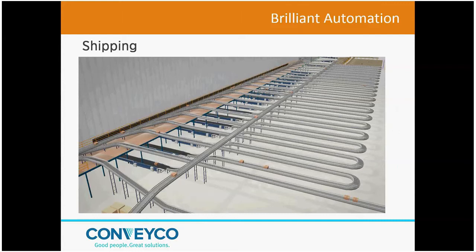In a piece picking operation, what this would handle is things coming from packing. You could have packing anywhere in the building, have a single stream come out of your multiple pack stations, and then sort this out by, if you're an e-commerce operation, you can sort it out by carrier or carrier type. Your next day air goes down line 1, 2-day ground the other. If you truly rate shop and use multiple carriers for the same type of delivery based upon cost, then you would have an appropriate number of lanes for shippers and classes of service.